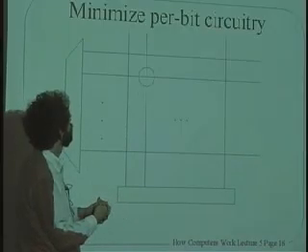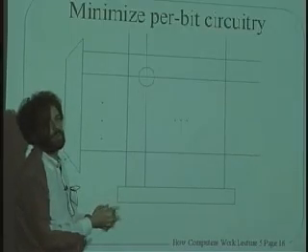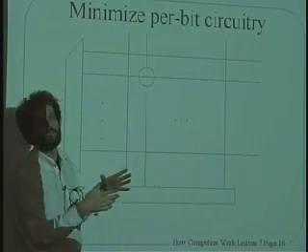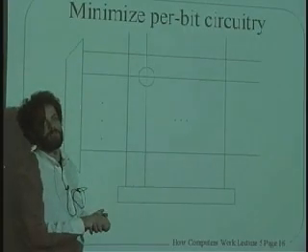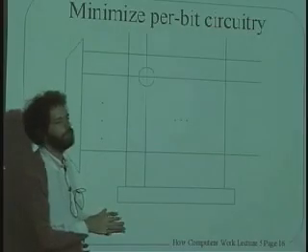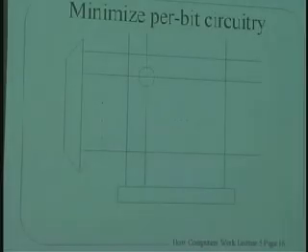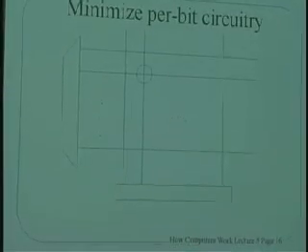Okay? And modern RAMs, or random access memories, are built like this, where we use the nice fact that 2D allows us to take the square root of the number of bits that we're trying to do. Okay, so for instance, a megabyte would be, so let's say we had 1 meg. We wanted to build a 1 meg chip, right? 1 meg is 2 to the what?